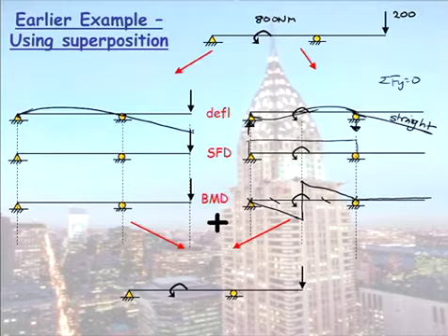It will deflect down like that. If you can't see that, buy that bit of flexible moulding from Bunnings. Get someone who you live with, your brother, sister, mum, dad, flatmate, to hold the ends and push down and see what it does. So, tell me now, at this roller support, if we take this roller support away, which way will it want to move?